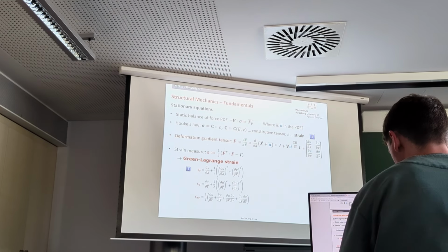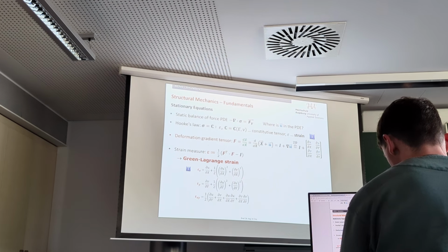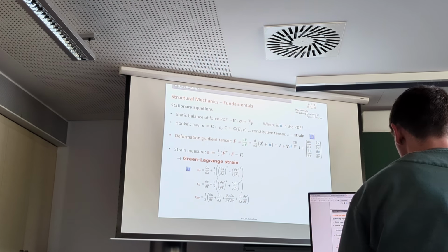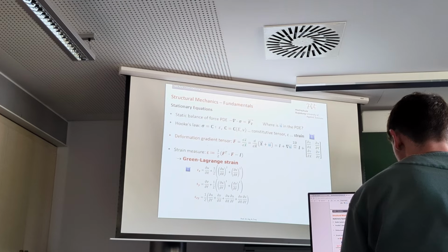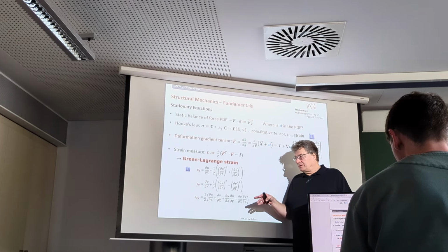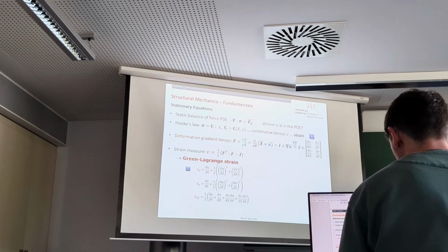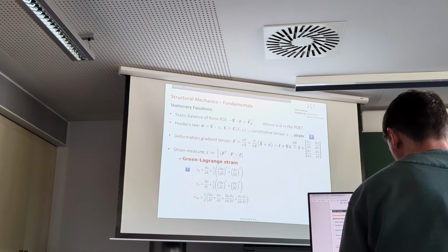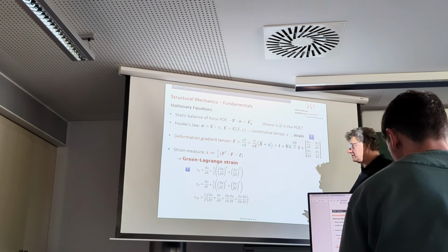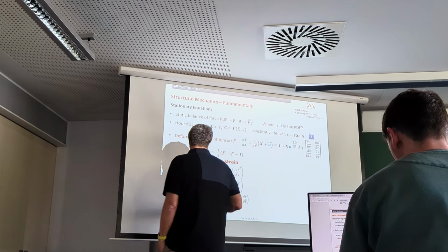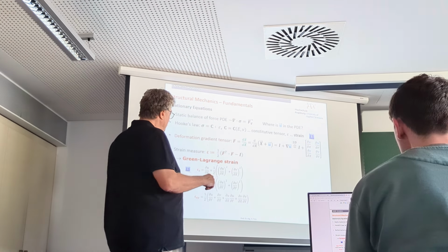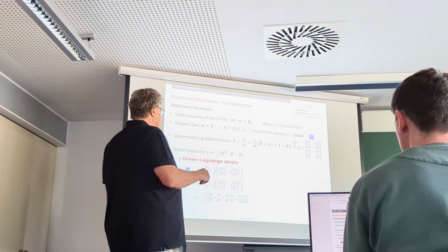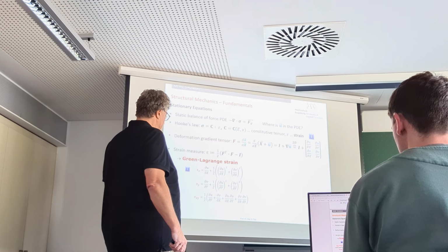Not complicated in the sense that the computer cannot solve it, but it's just numerical effort. And these things add up. So there are situations when you can make things simpler, when the displacements are very small. And for those situations, you can enable in COMSOL simplified versions of that exact Green-Lagrange strain formulation.